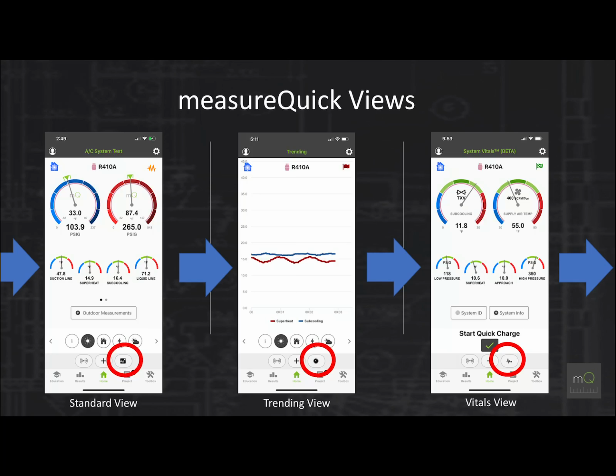But if you tap on the trending button, that'll take you to a trending view. And like right here, you can see what I'm looking at is superheat and subcooling. So I can see I have a TXV that's hunting a little bit. And then I can tap that trending button again, and I can go into our vitals view. And the vitals view is really designed for like a one-page view of measureQuick.